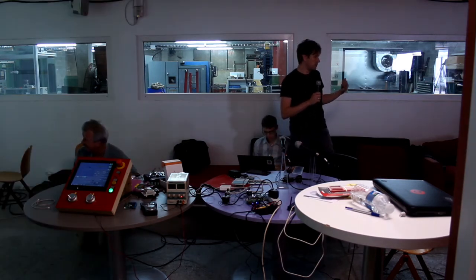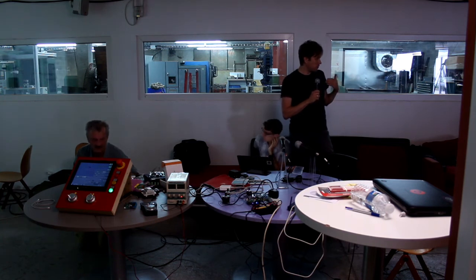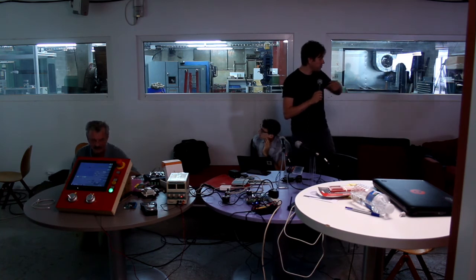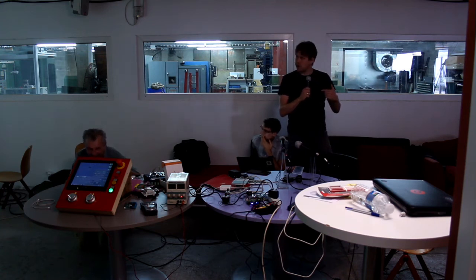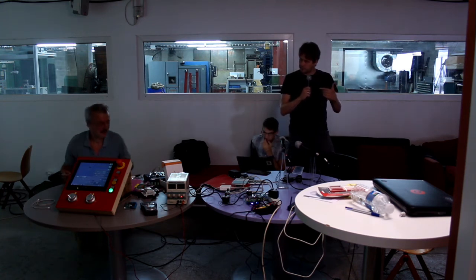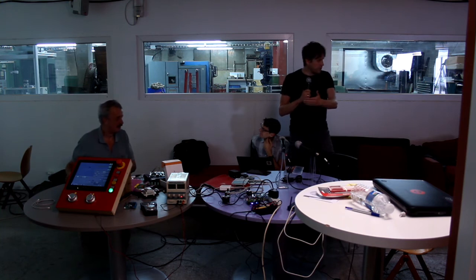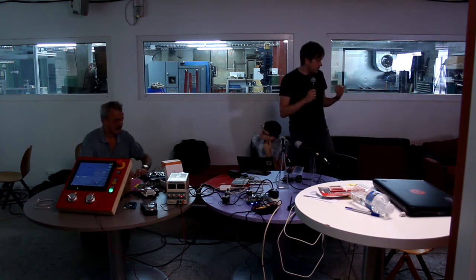It's like the G codes normally in a CNC application will be converted, will be interpolated. So if you have an arc, it will be cut down into small straight lines. And these straight lines are being interpolated and put into the configuration which will then make sure that the pulses will actually happen.